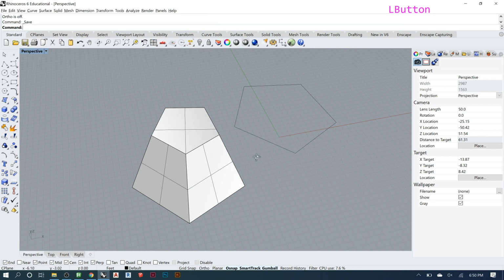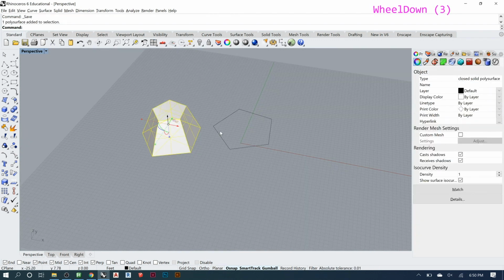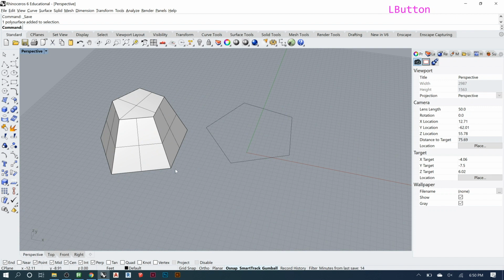So let's ignore that. If I wanted to do a command, let's say move, and you don't remember how to move, and you're looking for move everywhere and you don't see it, you can start typing like you would in CAD, and Rhino will try and fill in. It has this command line, and as you type, it's smart and it will fill in all the possible commands. And the more you use a command, the more often it will recommend that command at the top. So it starts to learn what commands you like to use, and your most used commands will start getting suggested faster and faster.